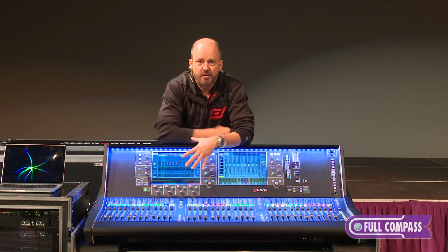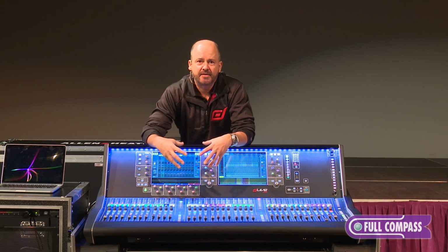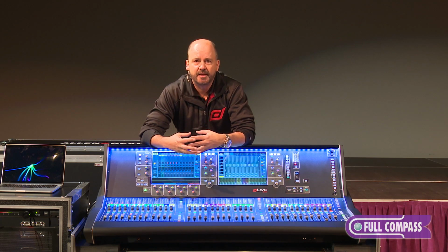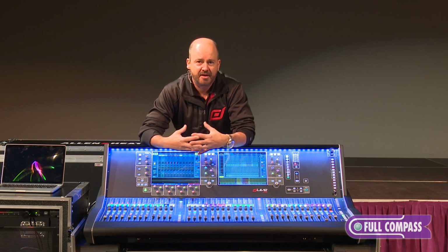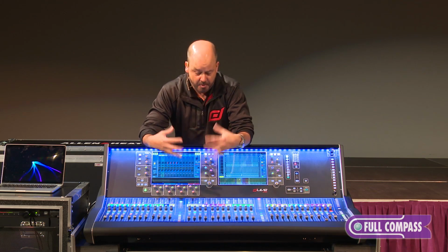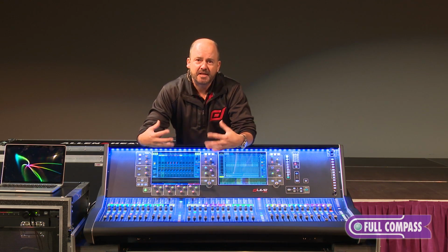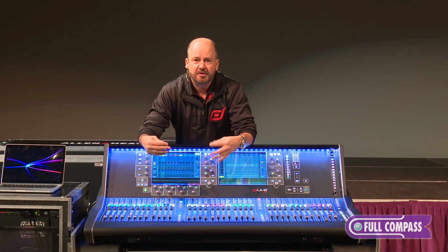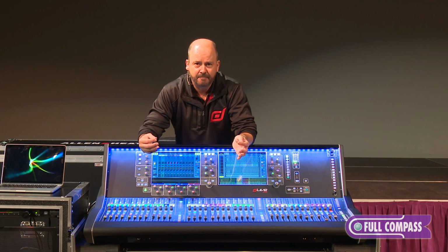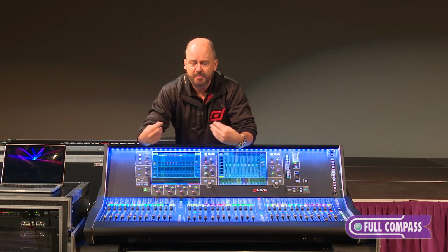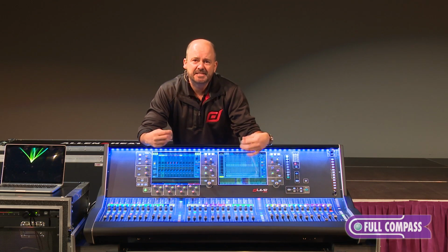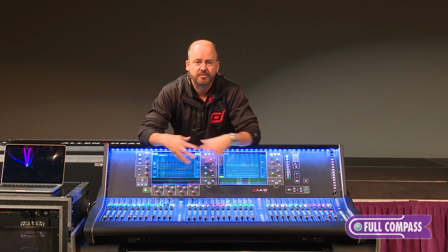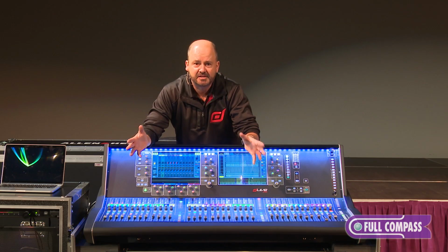The dLive is one of the first products in our family that offers our new deep embedded plugins, which is actually our dynamic effects emulation processing on a per channel basis. We actually have the capabilities of up to 6 different compressor models on every input channel, as well as preamp modeling, parametric EQ modeling, and 16 rack effects built into the system, again, all running at 96K sample rate.